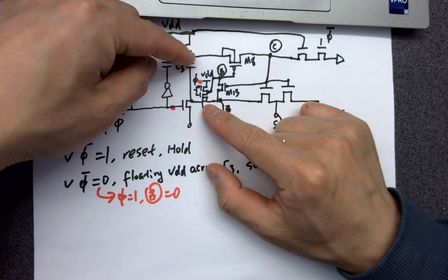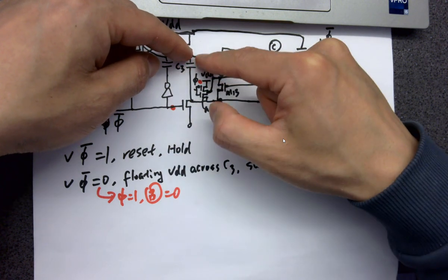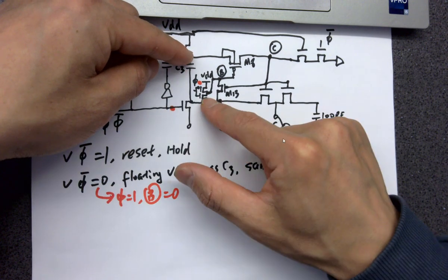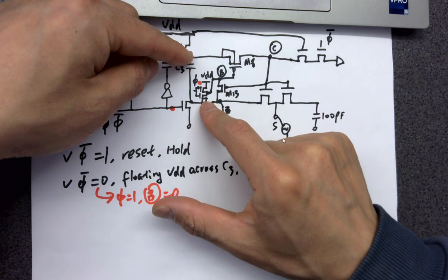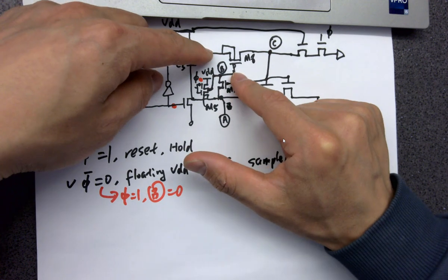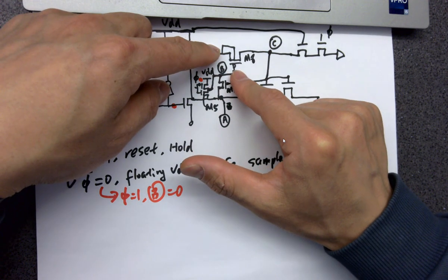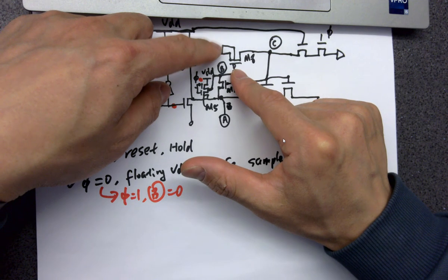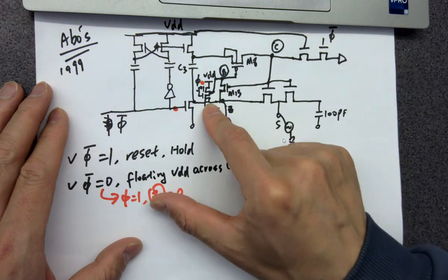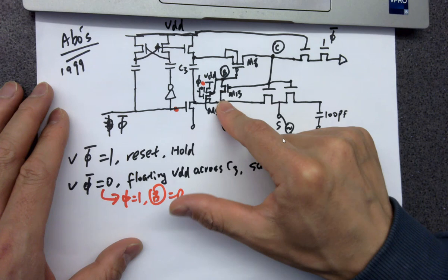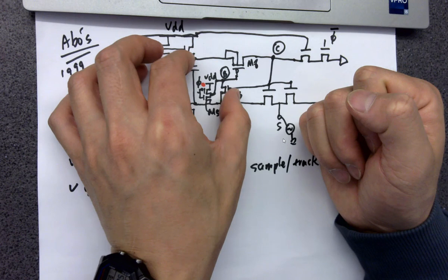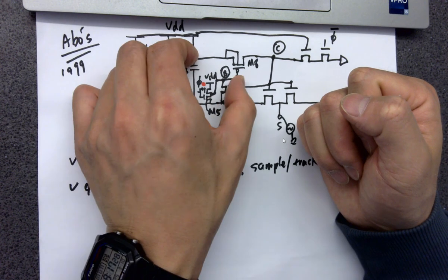If you're looking at the top of the plate of the VDD, the top of the capacitor, you can see this wire is being shorted to this point through this NMOS because the NMOS is on, right? So it's forming a short circuit to B. So it's basically applying VDD across VSG. Do you agree with that? Phi is on, NMOS is on. This wire here, A, so A and B is basically, VDD is basically added to the VSG of the PMOS